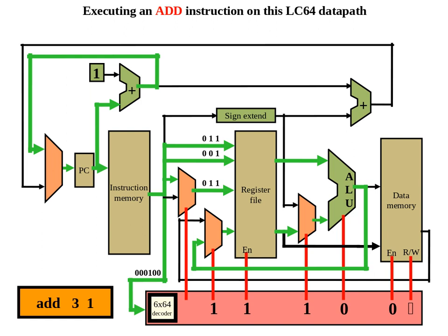Because of our decoder, hey look, these are our lines to our muxes and our enable bits, which will help us determine what should be what. That should be a 0 right there. It's an orange 0. So this is a 1 here to signify you take the 1 element, aka the second input, and you forward that to the ALU. So you are forwarding the 2 values read from the register file to the ALU. We'll say 0 is the add, so then the ALU would add it, send it back here, which goes to this mux, which is saying that you want to read from this input.